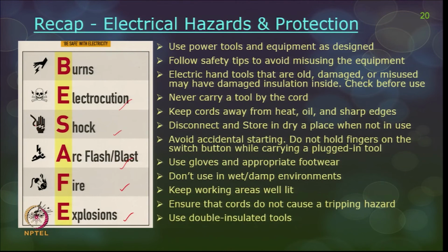Never carry a tool by the cord, keep cords away from heat, oil and sharp edges. Disconnect and store the tools in a dry place when not in use. Avoid accidental starting, use proper PPE. Do not use electrical appliances in wet or damp environments, keep working areas well lit, ensure cords do not cause a tripping hazard and use double insulated tools.